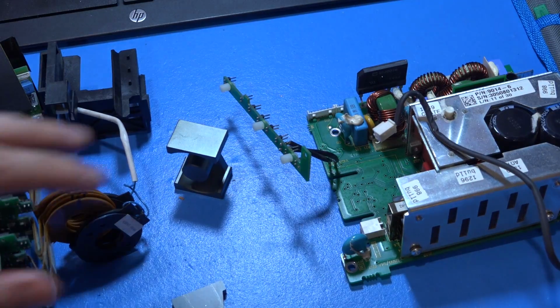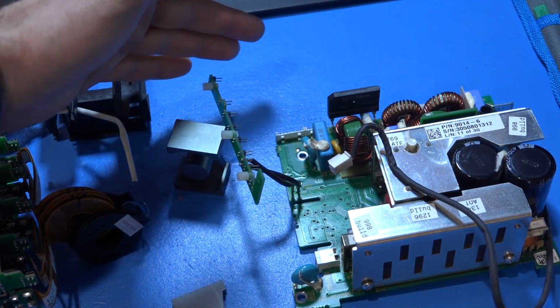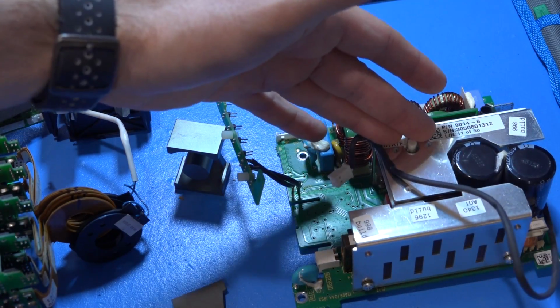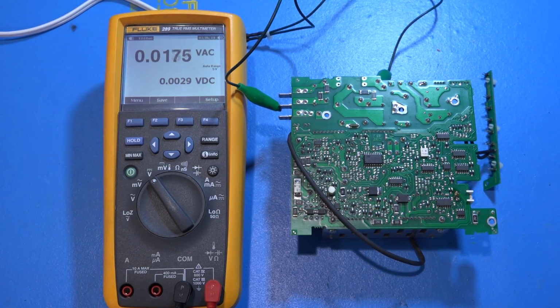So the very first thing we can try is we can, of course, bypass the fuse on this and find out why the fuse is burning up, and find out if there is a problem on the primary and where that problem is. So let's go ahead and set that up. I'm going to use my isolation transformer at much lower voltage. We can slowly crank that up and see if we see any issues. Okay, let's do some measurements.